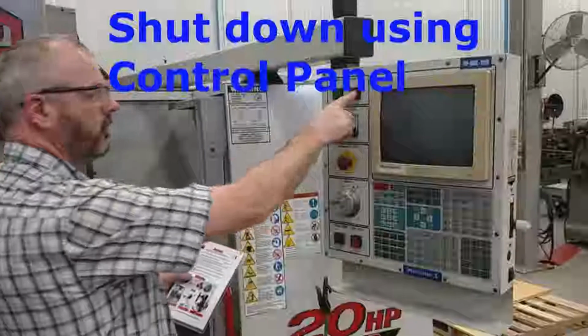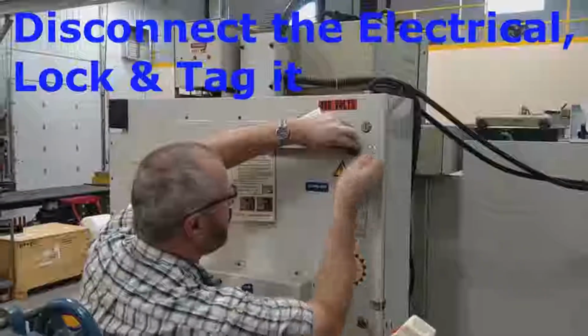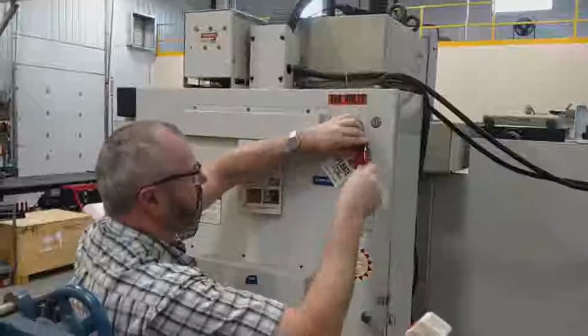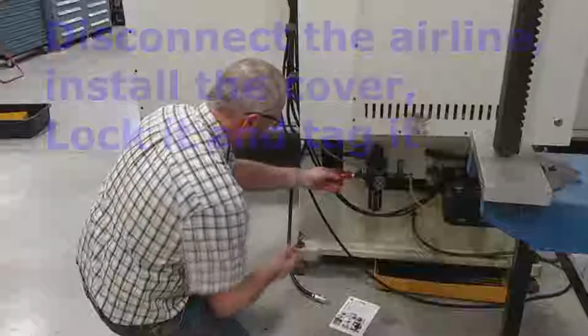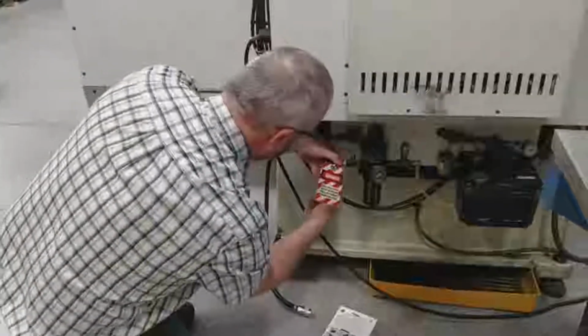Shut down the head using the control panel. Disconnect the electrical supply by turning it to the off position, then apply your lock and tag. Disconnect the airline, install the cover, lock, and tag it. Finally, verify the machine is dead by trying to restart it at the control panel.